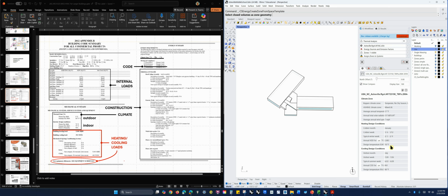These will be different in New York City, and these are set by standards, and we're not going to get into the basis of that. But you can imagine if we're running a simulation, those design temperatures are going to have an effect on the peak heating and cooling loads, right? If we say I need to experience temperatures that are 0 degrees Fahrenheit and have a system that will be able to heat when we get that low, that's going to be a different system than if we're saying, no, the lowest temperature I need to worry about is 18 degrees Fahrenheit.